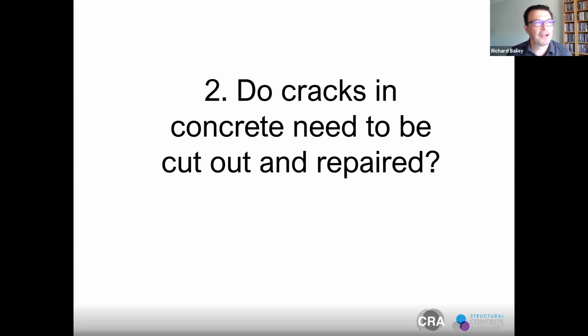Yeah, because I'm passionate about that with everything that we do in our business. It's wherever a destructive test can be undertaken, i.e. an intrusive test, a core. Taking a core through a crack is a fantastic way of demonstrating full depth penetration. If that's an absolute no-no, depending on the structure, then there's various non-destructive testing techniques that can be used, ultrasonic pulse velocity and one or two other things to determine the integrity of the filled crack.